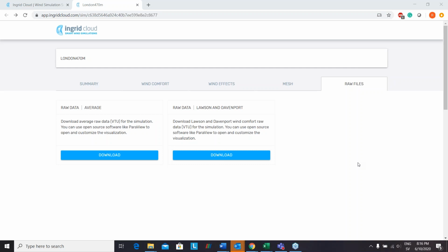And by refining the mesh properly, this means by refining the elements which contribute with the largest error, you can reduce the error in the quantity of your interest. So it's an automatically adaptive mesh refinement.